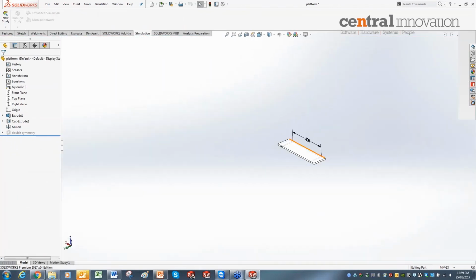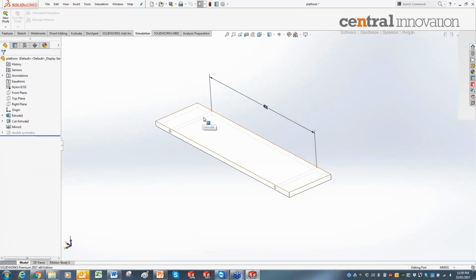So this is the plate I'm going to use. As you can see here, this is the distance. The 400 mm is the distance between the two link connections or the rod connections. I want to change this gap and see how it is affecting the performance. Can I use a lesser value for this distance? Or if I increase the distance, how is it affecting my stress and deformation?